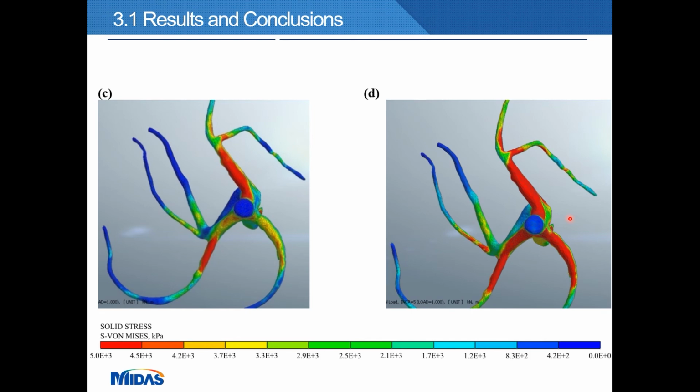So using numerical modeling, it was possible to estimate the effective length of the roots that provided structural resistance under lateral loading. In this case, the threshold value used to define the tree protection zone, as it is called in agriculture, was the minimum concentration of the stress, limiting this minimum stress condition of the roots to 5% of the maximum computed value.